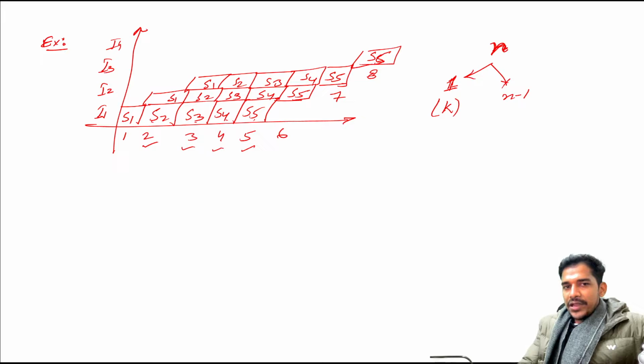So this is happening in parallel. So these are not extra cycles. The I2 instruction is using only 1 extra cycle, and you will see that the I3 instruction is also executed in 1 cycle. That means in the 7th cycle the 3rd instruction is executed, then in the 8th cycle the 4th instruction will be executed, then in the 9th cycle the 5th instruction will be executed. So like this it will keep happening. That means the remaining n-1 instructions will take only 1 cycle each.